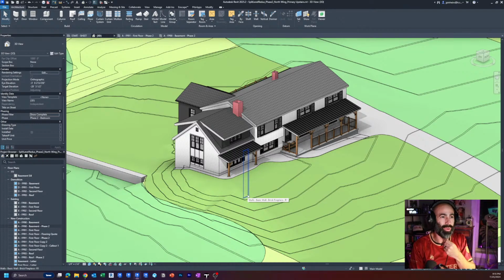But I usually do it on most of our projects: I will suggest you export the site separate from the building. This way, when you're constantly updating the building, your site is staying the same. Because what you're going to see here is that when I do refresh the site, I may lose some of my scattered vegetation like grass and so on and so forth. And you cannot do that if you do Direct Link. You have to do whatever's in your view.